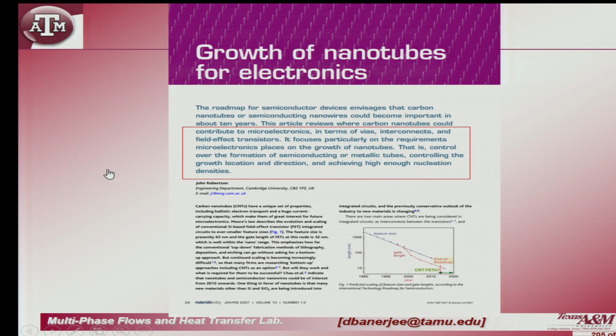We also had a grant from DARPA, a small seedling project, where we were trying to make carbon nanotubes using the dip pen nanolithography process. The idea was you deposit catalysts, and then you put it into an oven, and if you expose it to methane or ethane or acetylene, wherever the catalyst is, it finds the catalyst and grows into a carbon nanotube. That was the whole idea.